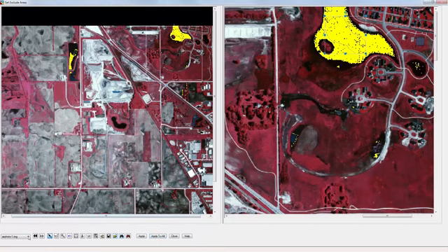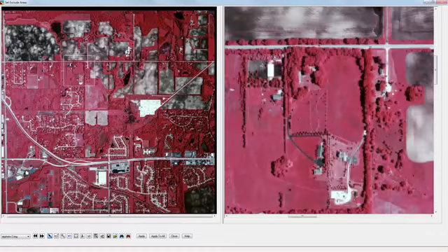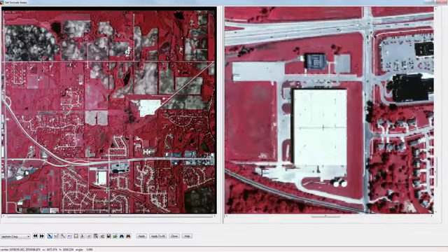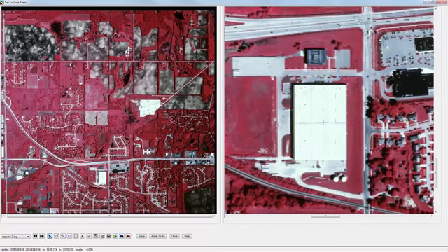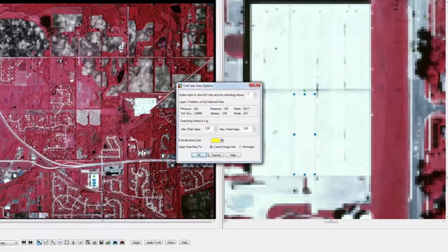Use the drop-down menu to select airphoto2.img. Use the link view to zoom in to one of the buildings. Digitize a polygon within a group of white pixels, being careful to exclude any dark pixels within the rooftop of the building. Click the Find Like Areas button.